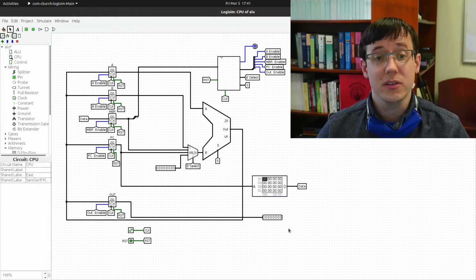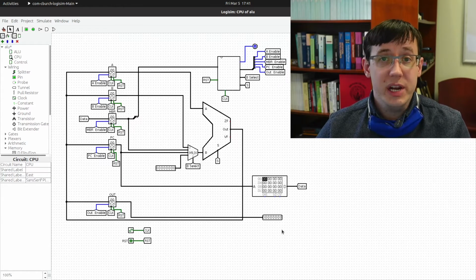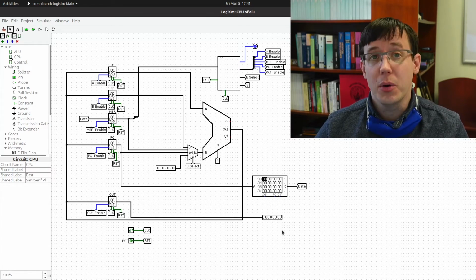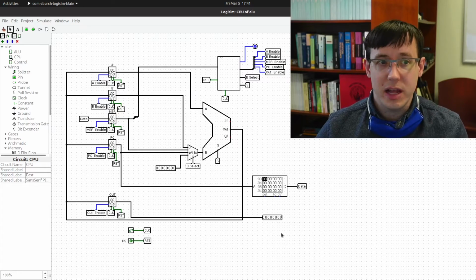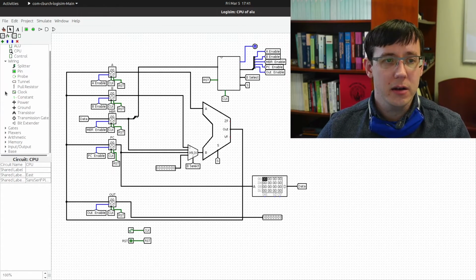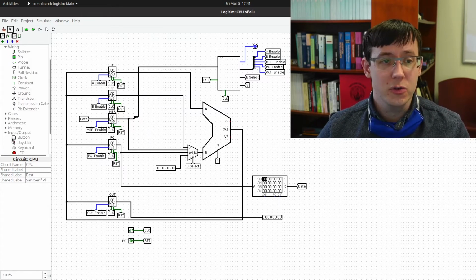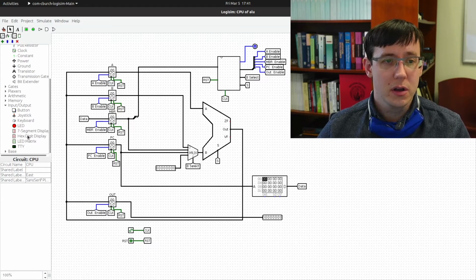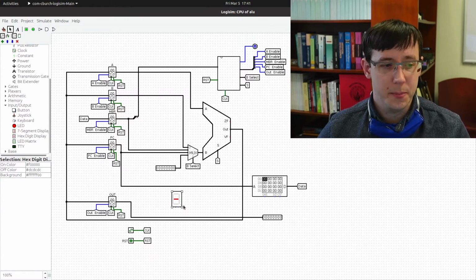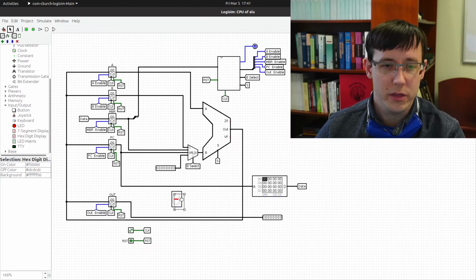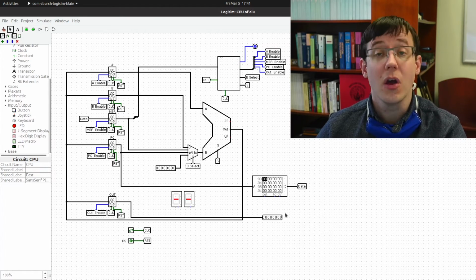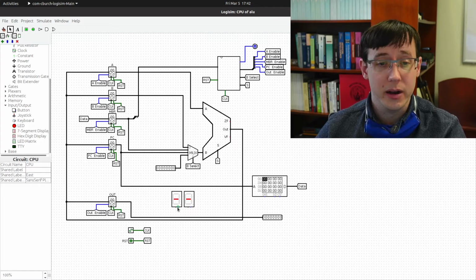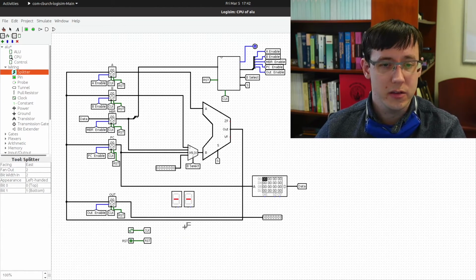And we can now see this output in binary. But it would be nice to not just view this in binary, but also to view it in hex, because that's much more readable. And in Logisim, we can choose the output component called a Hex Display. And with 2 hex digits, we can display 8 binary digits. And so now we can use a splitter facing north, switching its handedness.